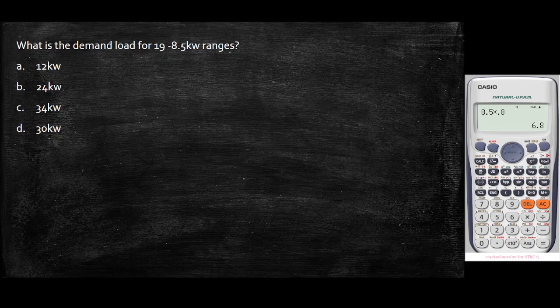Okay. So, balik po tayo. So, we will be solving this one. What is the demand load for 19 8.5 kilowatt ranges? Okay. Solution. So, 19 siya, no? So, we'll have 8.5 times 19 kilowatts.